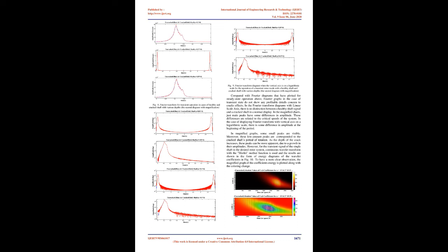As the next step, from the responses of the desired system, the continuous wavelet transform with the Morlet mother function and for the scales of 1 to 128 has been done. The diagram of the energy coefficients of the wavelet is also shown in Fig 6.